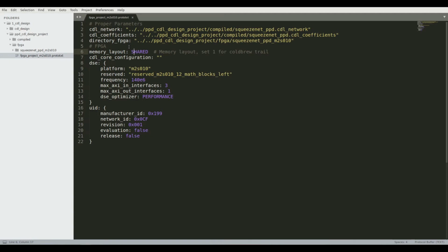So you can ping pong between them: let's say you're processing one network and then you're uploading the results of the previous run and downloading data towards the FPGA, so it has the data for the next iteration ready. And then it has a shared heap space, so it minimizes memory use by reusing this shared heap space for all the intermediate layer processing.